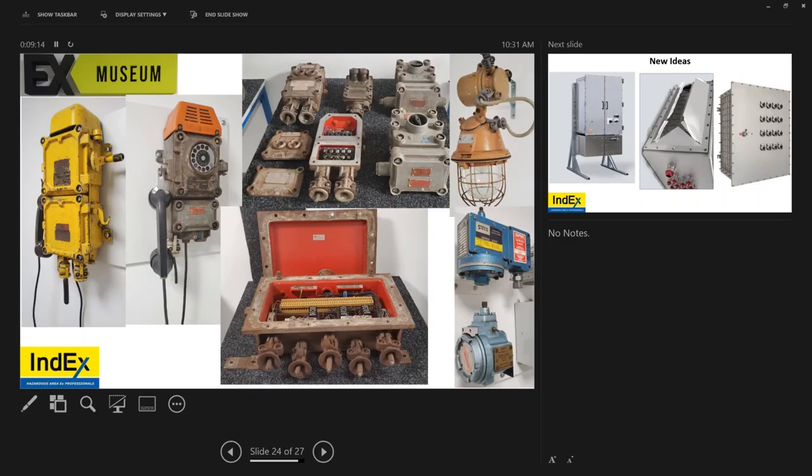Are gas groups based on minimum ignition temperature? Note, this is not the same as equipment group as stated. Yeah, it's based on minimum ignition energy and its LELs and ULs. There are many different considerations, but it's ignition energy and also its temperature class. It depends on what gas it is, but usually it's minimum ignition energy. So hydrogen, acetylene, and there's another one, carbon disulfide, I believe. These are 2C. These are the most dangerous.